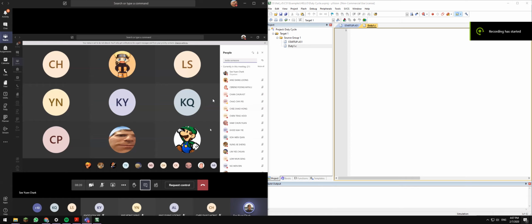PIC24. So from PIC24, yes, I can migrate to other types of microcontroller like STM, or this morning we're using Atmel AT89S8253, or even, okay, if you have ESP32, you can even migrate to ESP32. Okay, so you must remember ESP32 is a bit straightforward. We just call the PWM library function. That's it, done. You know, you can generate 30% and 50% duty cycle.